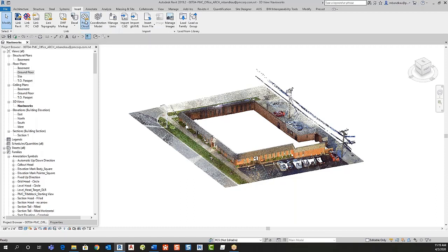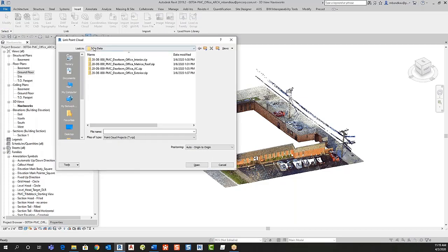And right now it's going to bring me to the folder where all of my point clouds are stored. You may need to scroll through your machine and find the file location for a file you want to bring in. Types of files, because this is an Autodesk project, Recap, RCP files, and the CAD export, the RCS file, are our options.